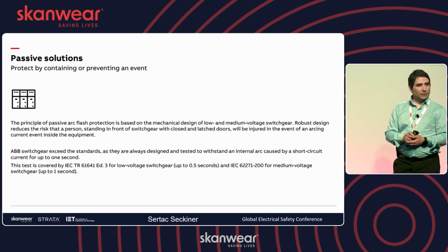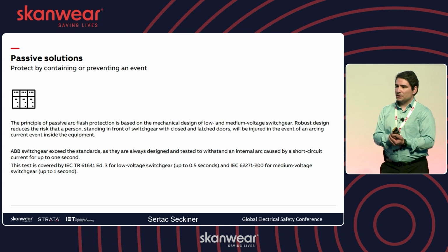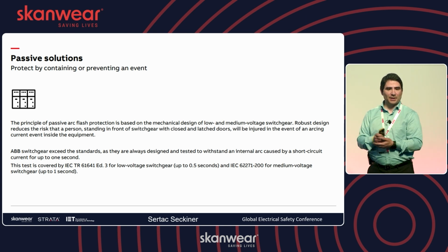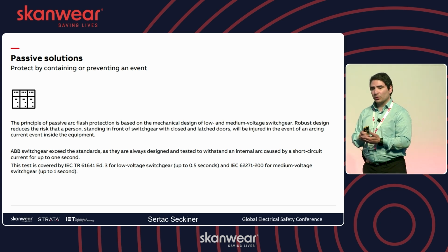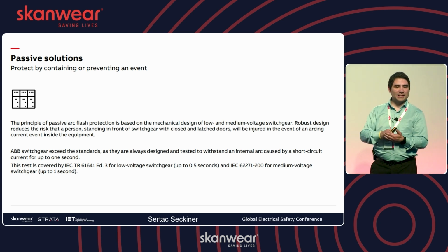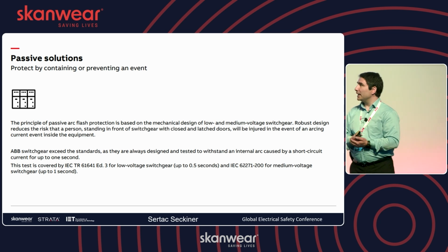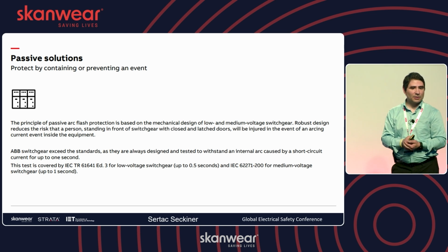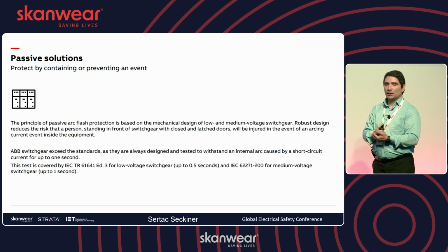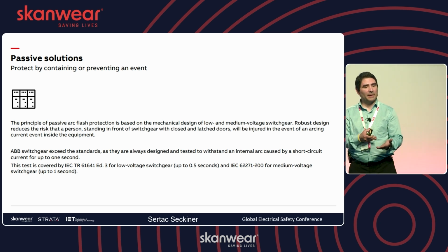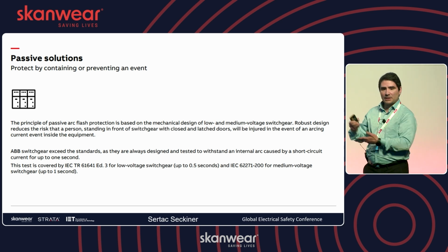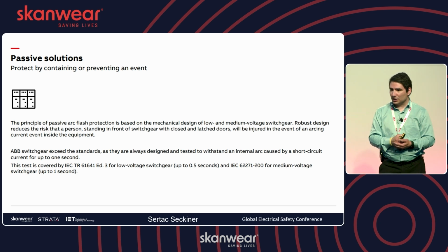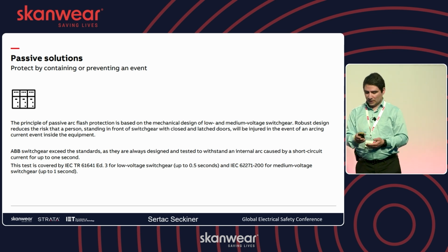Starting from the passive solutions, as I mentioned, we need to build our switchgear very sturdy. So we need to comply with the regulations and the standards. And as Marcin mentioned, we need to always exceed the minimum requirements. In ABB switchgear, for example, we always strive to exceed it. In low voltage, we have half second withstand capability, and in medium voltage it's even higher, because obviously in medium voltage we've got higher energy levels, 1 second withstand levels.